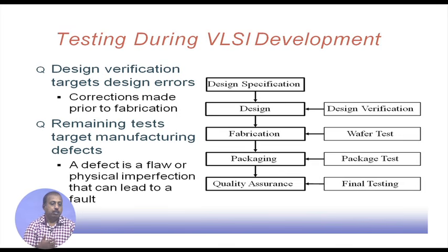It may be that we do it in some hardware description language, VHDL, Verilog, etc., or it may be that we write it in some other specification technique, from which the conversion is done to the behavioral description or structural description of it. Then after this specification is given, it passes through some design process, basically through some CAD tools, from where we get the design.